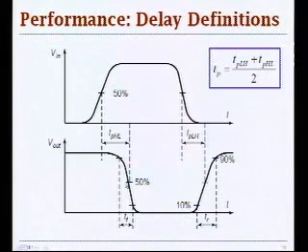So you have the fall time that takes this waveform to go between 90 and 10% transition points relative to the full voltage swing, and also rise time, which is between 10 to 90% of transition points. And later in the class, we will introduce a correction for this delay formula. You will have basically the propagation delay of the gate itself plus some linear term that is proportional to the slope of your input signal.